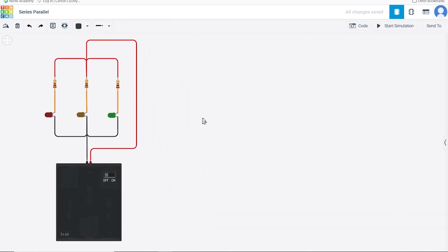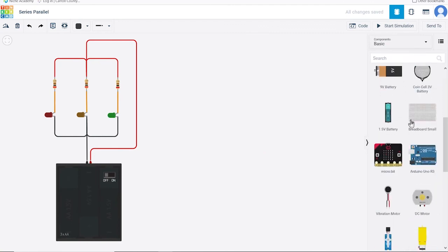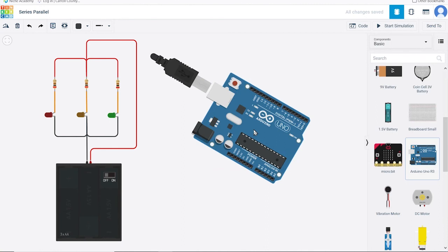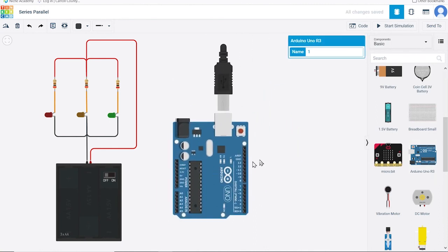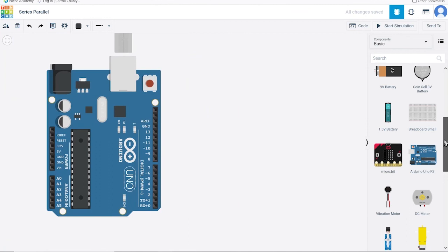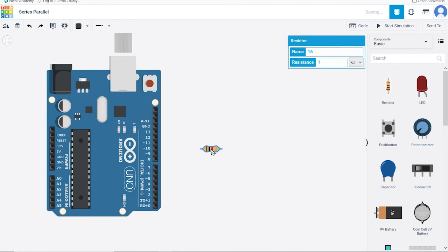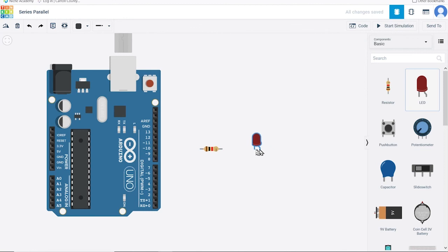Now let's see how current limiting resistors can be applied to an example Arduino project. In many cases, we may want to have an indicator LED that signifies some event or condition in our project, or a method to get visual feedback when an event in our code takes place, or is absent. We'll start off with importing an Arduino Uno and connecting a red LED and current limiting resistor. We'll explore in later videos the multifunction nature of Arduino pins. For now, we'll use pin 10 on the digital side to serve as our positive terminal, and ground on the Arduino as our ground terminal.